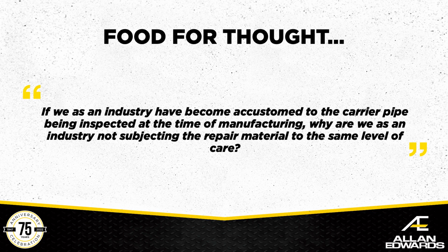But there's nothing to say, did the sleeve I put on meet some sort of criteria? And so if you think about why it matters, right? If you know that that steel is of the right thickness, free of laminations, gouging, other internal flaws, you're able to get a much higher quality steel sleeve product. So food for thought. And I think this quote actually summarizes it quite nicely.